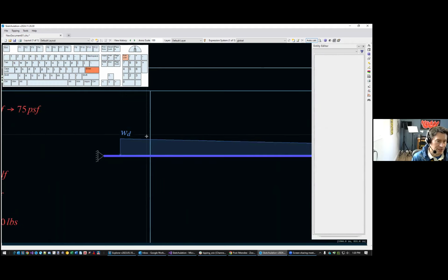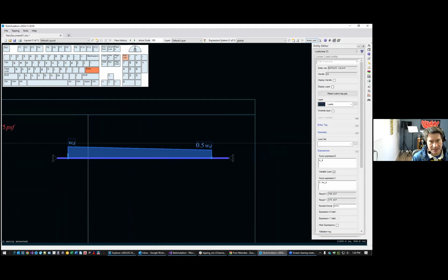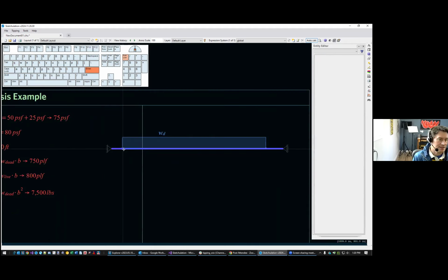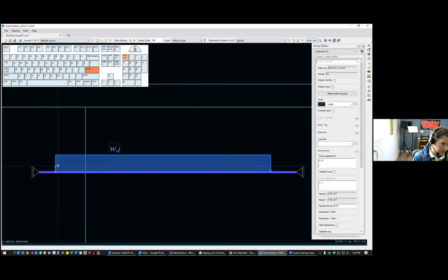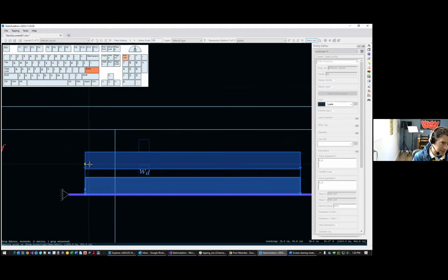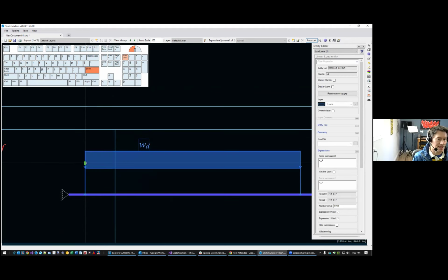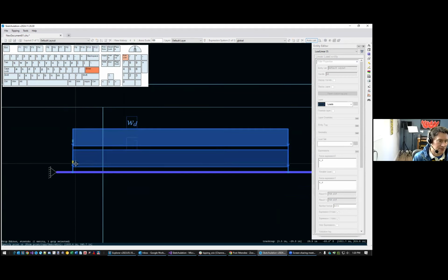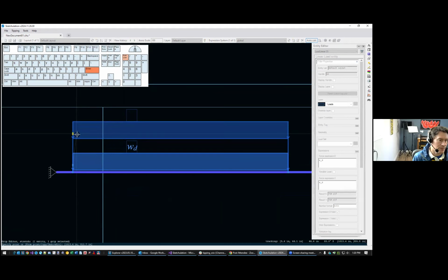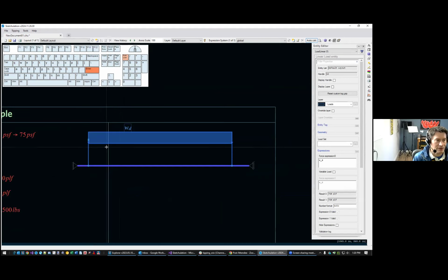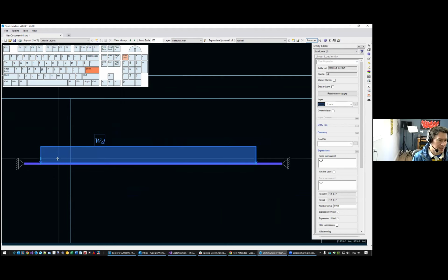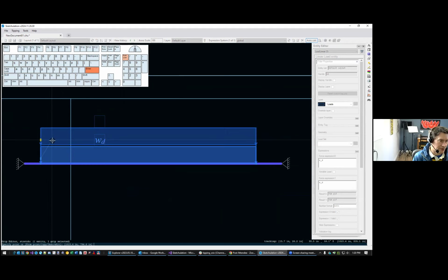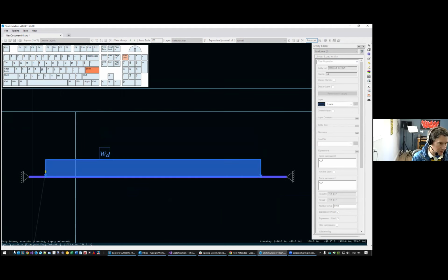Okay, so I have my dead loading defined. I'll go ahead and just make that not variable anymore because that's silly. And then I have my live load. I want to create my live load. You'll notice that there's a little grip here. You can select that grip and slide it around just to make space near the frame element. So it's just graphical. It's not changing how the load's applied. So usually, you put that all the way down, but it is helpful to take this grip and create a live loading. So I select the grip, and down at the bottom, you see there are certain options.